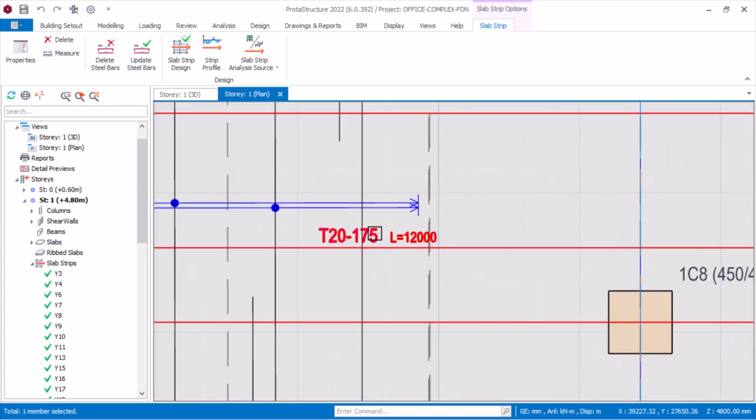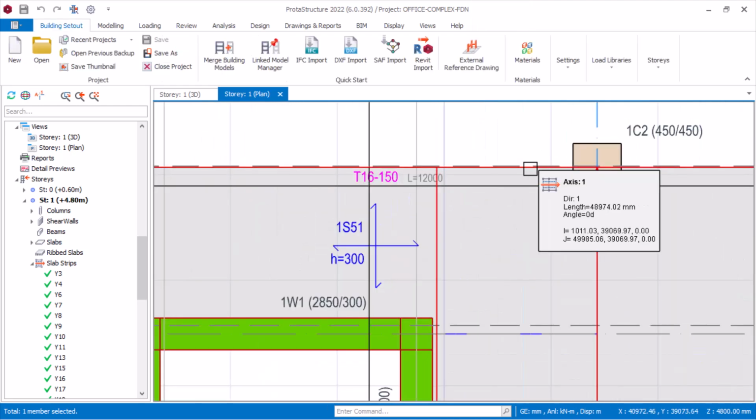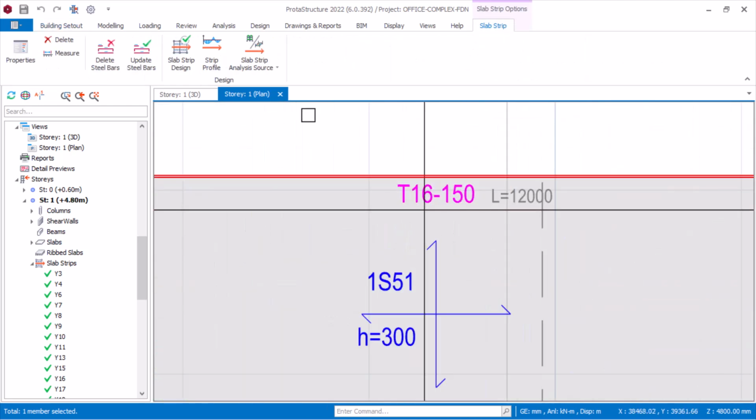Now it's time to introduce the punching shear reinforcement around the column region. Let me assume that you are having T20. If you're in Canada, that's H20, or H16. I'm talking about the bar notation.